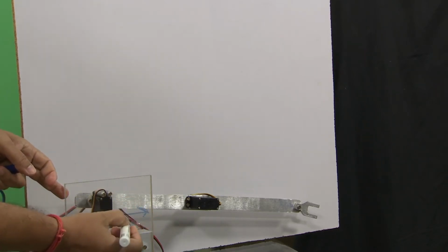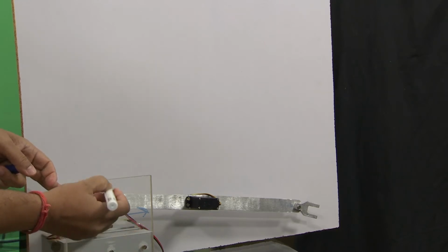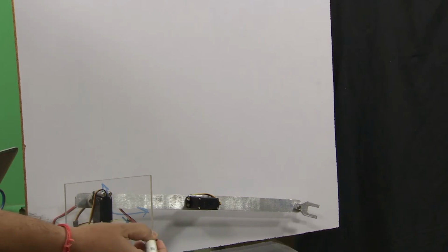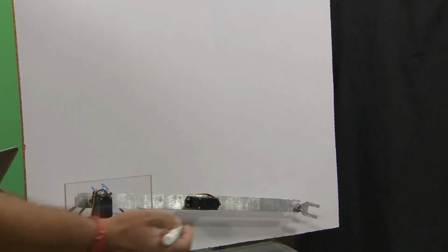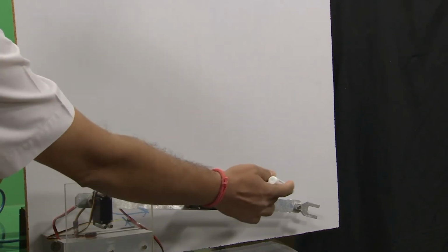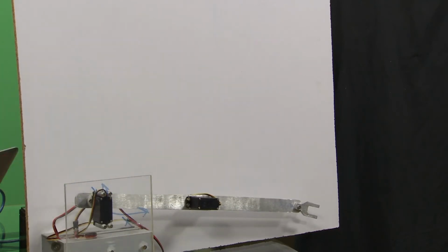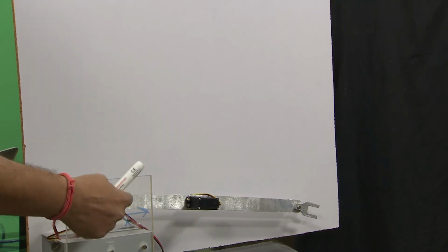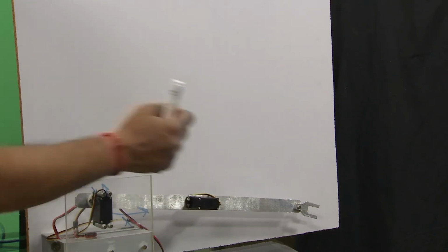Say I call my one axis here and another axis there. I call this my x axis, my z axis is perpendicular, and this is my y axis. Similarly, I put one axis on this joint and one axis on that joint. Now if I want to move the robotic link, I need to change the link variables. So we have one link variable here which is theta1, and there is another one there which is theta2.